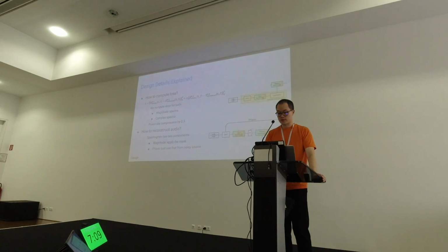When we reconstruct the enhanced audio, we need the full complex spectrogram. For the magnitude, we can use the one we get by masking the input. For the phase component, we directly use the phase of the noisy input without any processing.